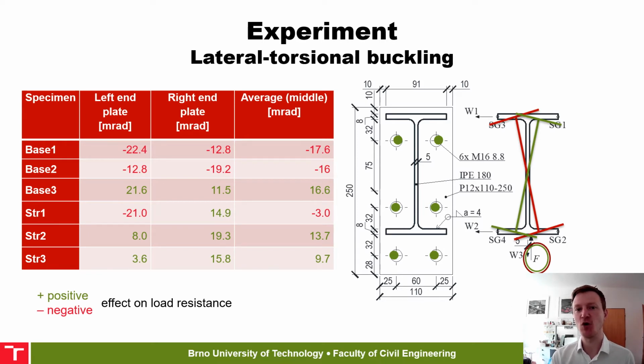Unfortunately, the bolt holes were not precise but with standard tolerances, and after the assembly, the beam was quite significantly rotated. Unfortunately, I realized this only after the 3 specimens with stiffeners were tested and disassembled. For the remaining 6, the rotations at the end plates were measured.